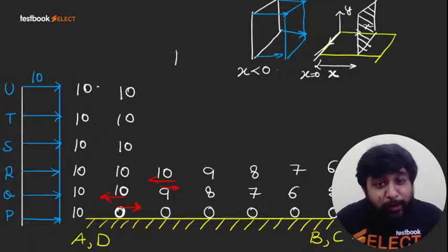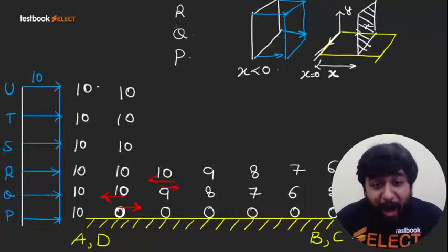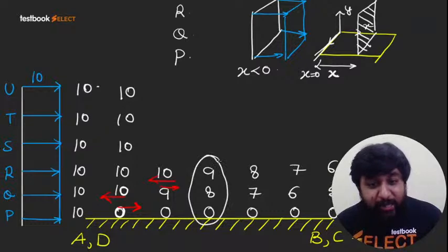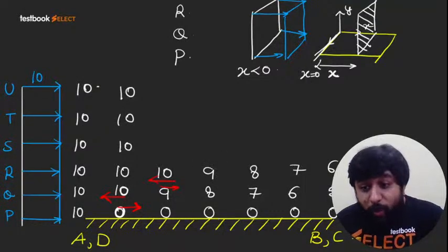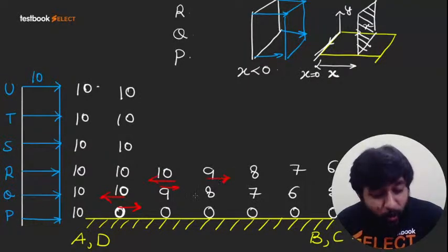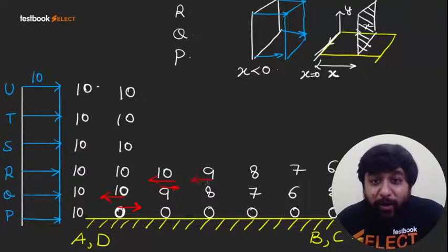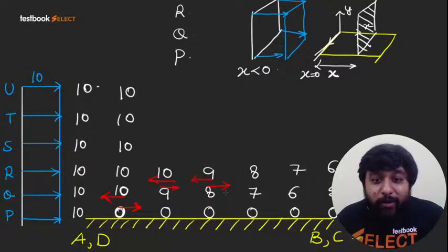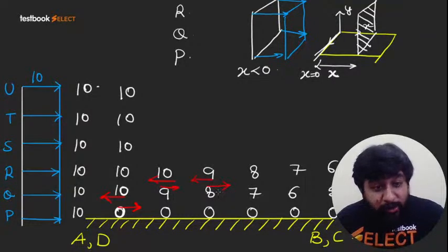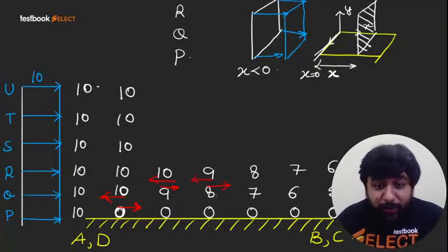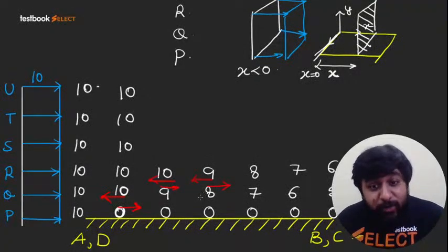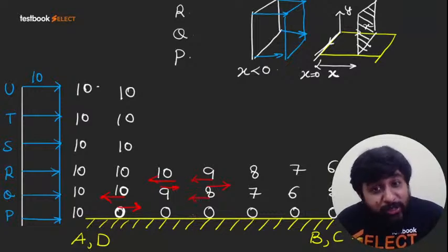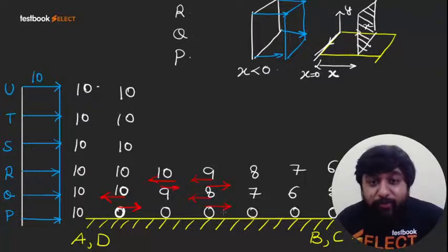Abhash is saying, sir, this is particle P, this is particle Q, and this is particle R. So, say for example, here, okay? What will happen? R is moving fastest. So on R, there is some shear stress in backward direction, है ना? Who will apply this shear stress? Q will apply this shear stress. So what will happen? Action-reaction pair. Similarly, between Q and P, there is a shear stress. But Q is moving faster with respect to P. So on Q, the shear stress will act backwards, and on P, the shear stress will act forwards.